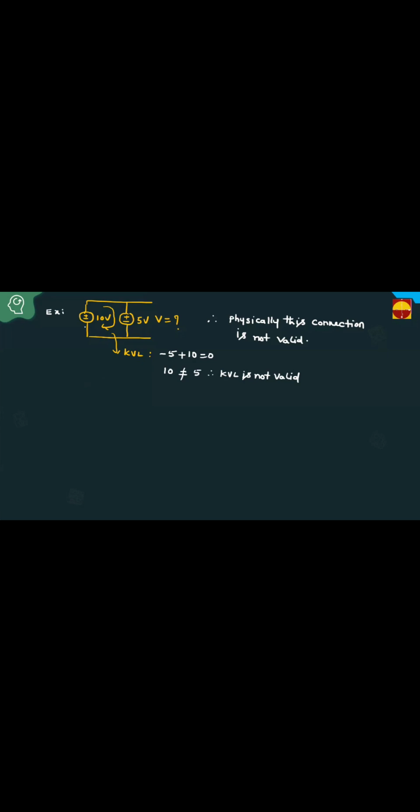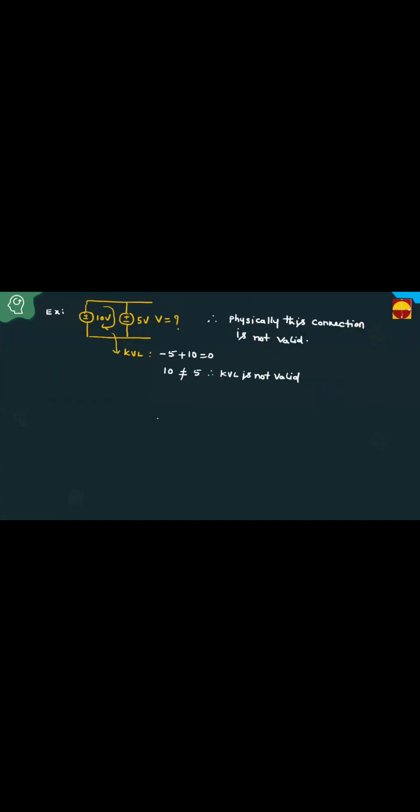You have to connect the two voltages in parallel. These two must be equal. If two voltages are equal, then only parallel connection exists. Two voltages must be equal and of the same polarity, plus minus, then only parallel connection exists.